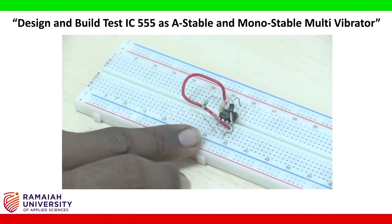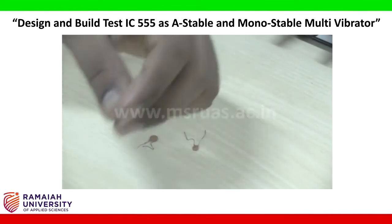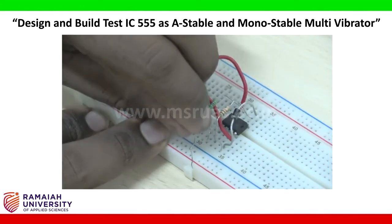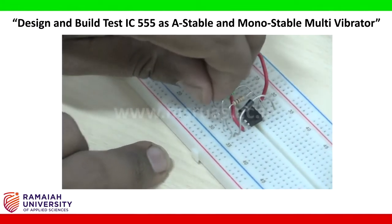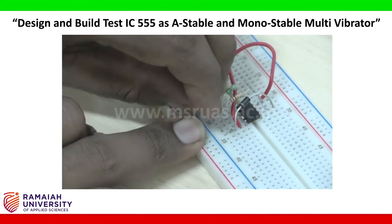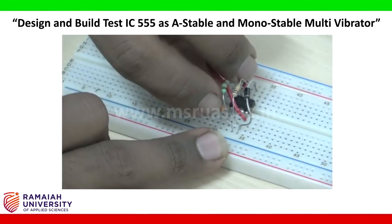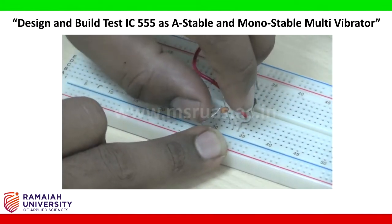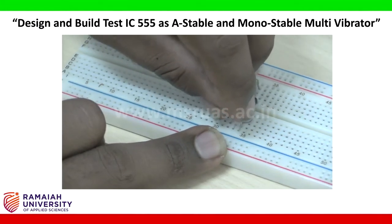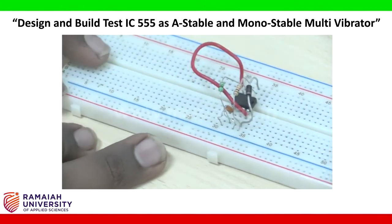Next I am going to connect the capacitors. The 0.001 microfarad capacitor will be connected between pin number 5 and pin number 7. First I connect pin number 7. This is pin number 7 and pin number 5 I need to connect. This is pin number 5. This connection will be over.